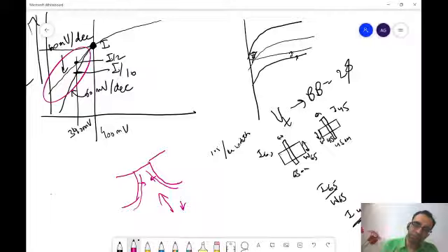So even without application of any voltage, there will be a connected depletion region across the source and the drain. We don't want that. We want that control to be available at the gate, so that only when a particular voltage is applied do we start to have a depletion region. Otherwise, VT will go very low and you will have lots of short circuit currents, lots of subthreshold currents. Therefore, you need to increase substrate doping as you go to advanced technologies.